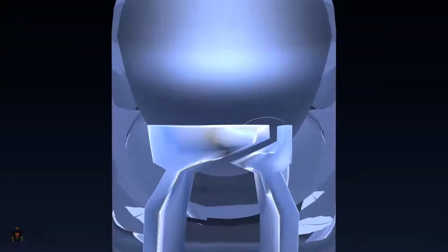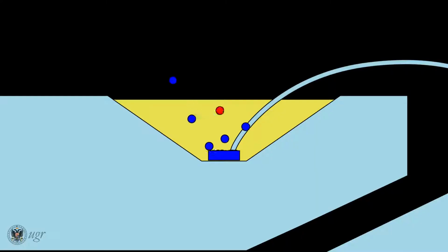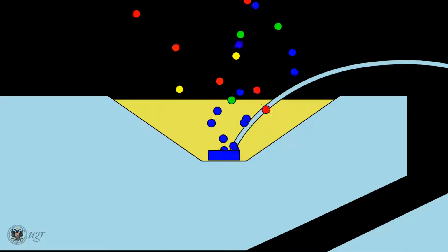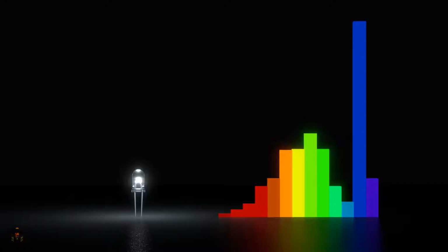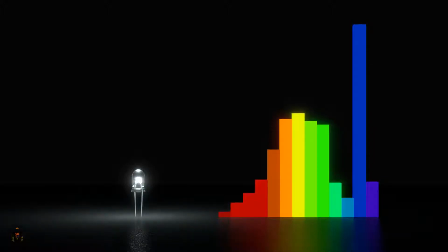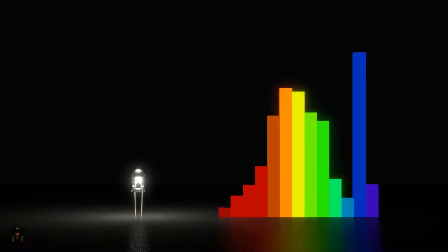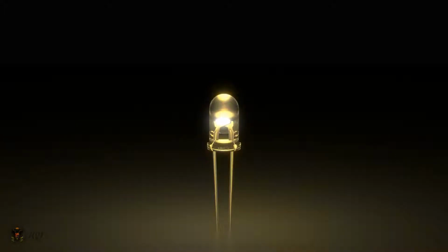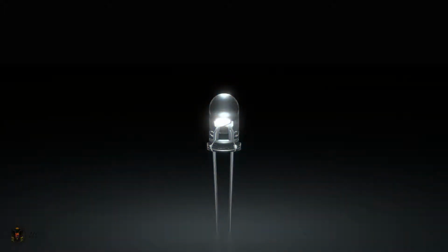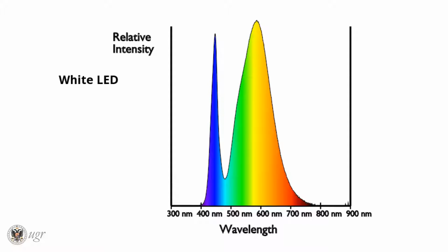Currently, the majority of the LEDs used in lighting are based on a blue LED coated with a fluorescent substance. This absorbs some of the blue light and re-emits it with longer wavelengths. The mixture of photons leaving the device is white light, which may have a bluish or yellowish hue if higher or lower energy photons dominate respectively. This depends on the well-known device color temperature. This is the spectrum obtained for a white LED, and we can compare it with the spectrum of sunlight.